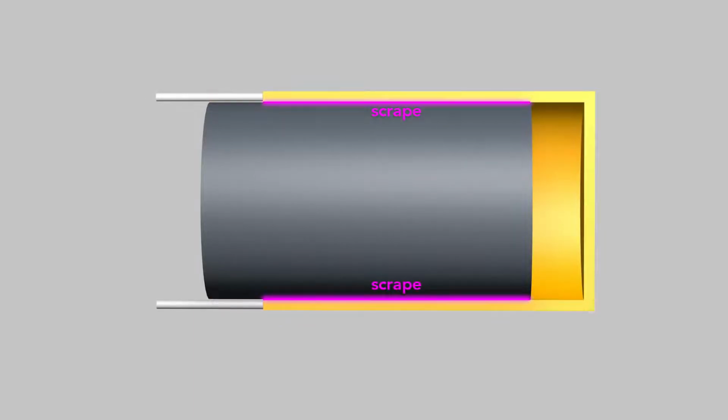Another very important aspect of mold design is the draft angle. If a part has walls that are exactly 90 degrees, it will be very difficult to eject because its inner walls will scrape the core half of the mold. Also, the vacuum will be difficult to break because air cannot readily enter.